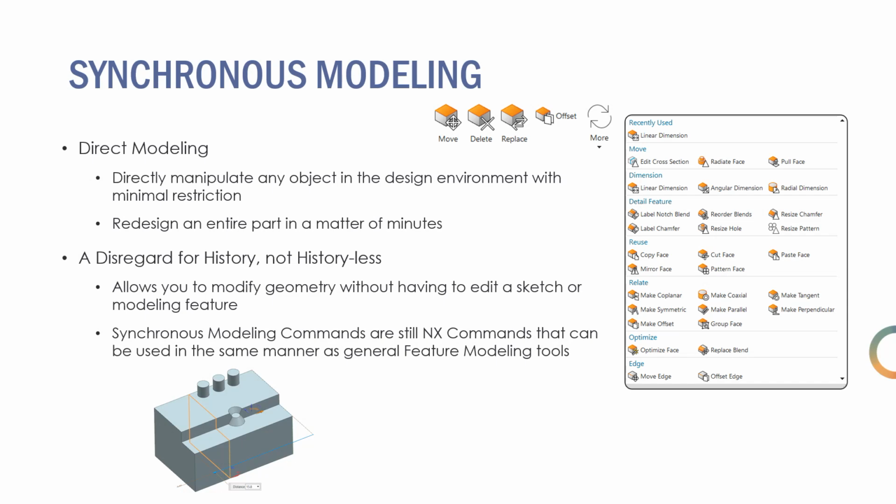There's also a set of tools that are specific to NX CAD, the Synchronous Modeling commands. I am a big fan of using these in my everyday modeling practices, and will make sure to spend a chunk of time going through what they can do for you. These tools will allow you to directly edit geometry that has either been imported or created with minimal restrictions. You'll be able to redesign any part in minutes, as well as make fast edits while not really knowing the history of the part. If it's an imported body, the part won't even have a feature history tree, but I can just move forward with the design using this set of tools.